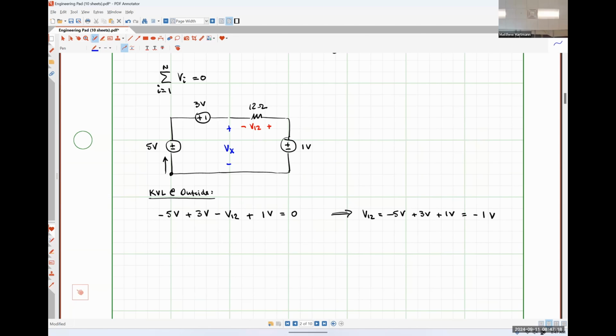Is there anything intuitively telling us that we can't determine this voltage? A lot of people seem to think that whenever we're applying Kirchhoff's voltage law, we need to be part of a closed path where current could flow. But really, I'm just looking for the voltage drop across an open circuited set of terminals here, okay?